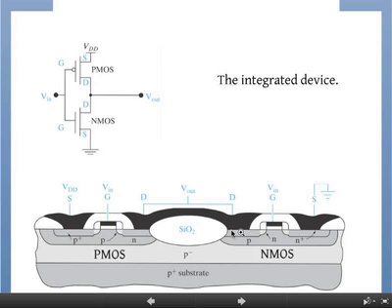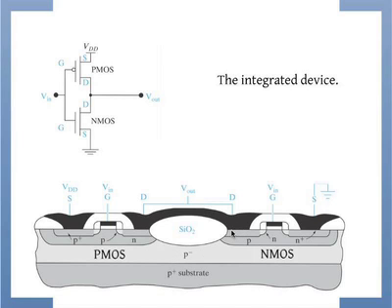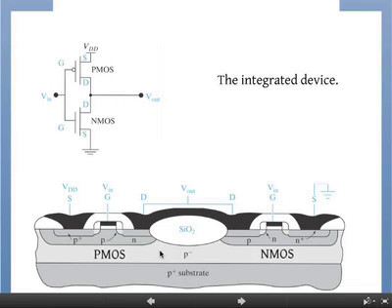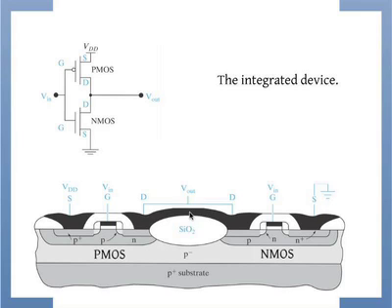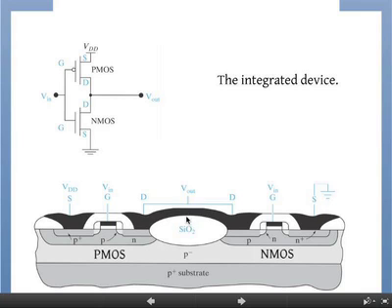And we talked about this. This is the parasitic FET, field effect transistor. To avoid that happening, you make this silicon dioxide very thick. In other words, you prevent this metal from acting like a gate. You're increasing the thickness, so no matter what happens here, you don't actually form a channel here. You put it far away, just like here. Okay, we saw this before.